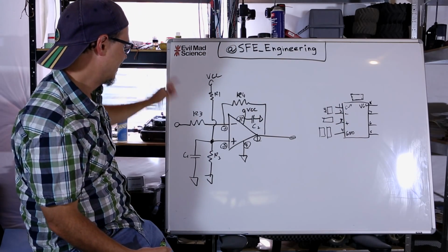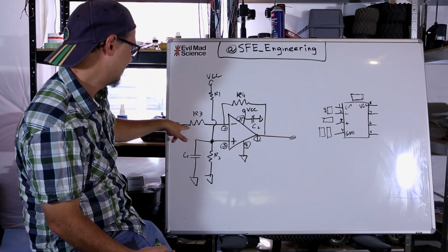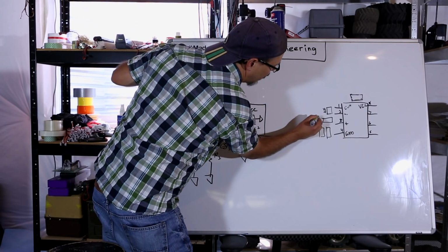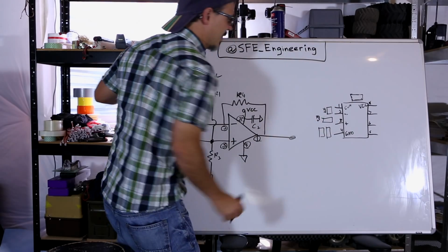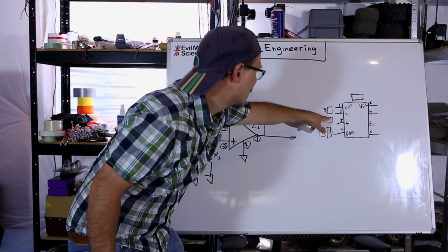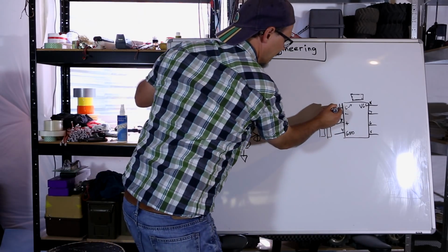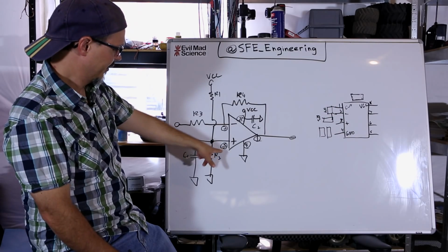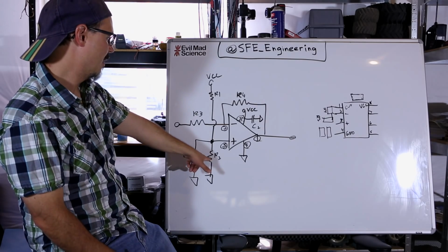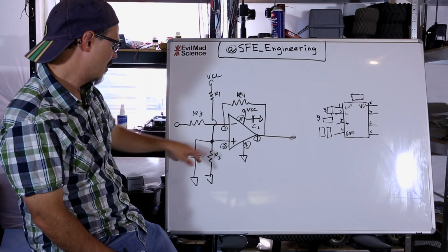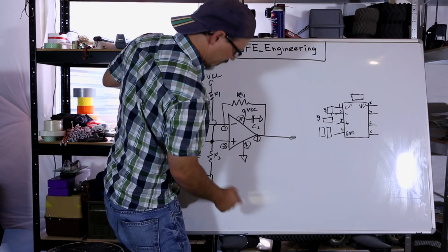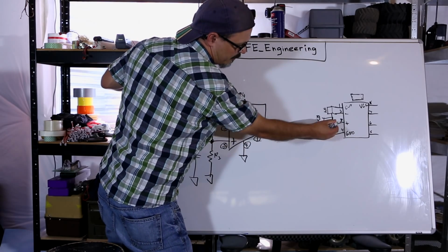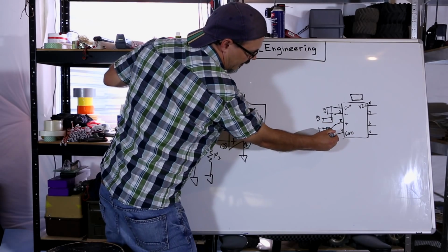The next, I've got my signal in also going off of R2. So I placed R2, it's sideways, what are you gonna do? Right there. So I can get to pin 2 electrically, right? And I will just run a small trace to these points. Aha, pin 3. What have I got on pin 3? Well, I've got 2 components. I've got R2, which sets the reference voltage with R1, and I've got C1 that filters. These both go to ground, so I can put those 2 components right across pins 3 and 4. So right there and right there.